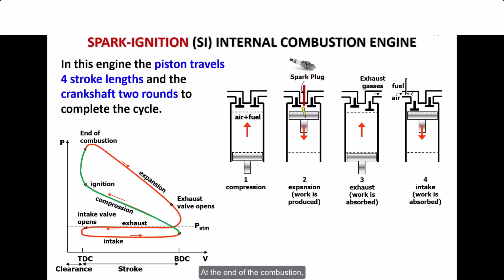At the end of the combustion, we observe a small increase of the pressure in the cylinder while it is expanding. This is because of the confinement of the reaction products in a volume which was previously occupied by air and fuel.